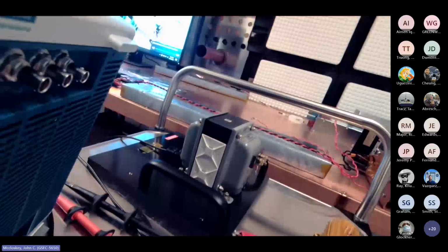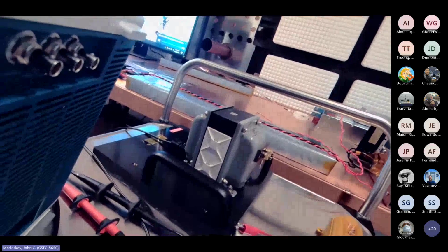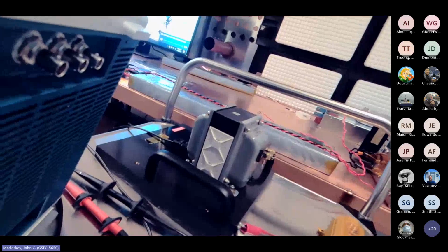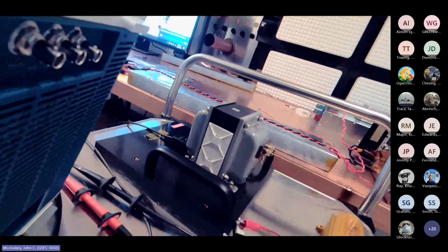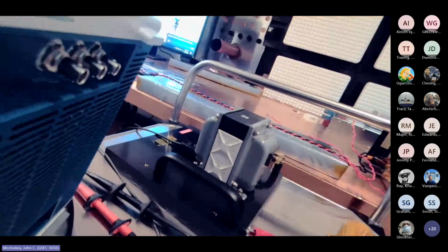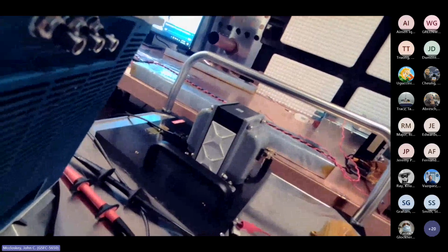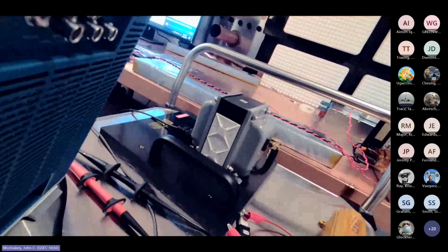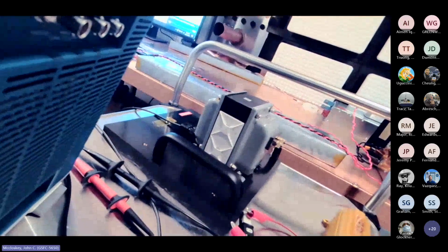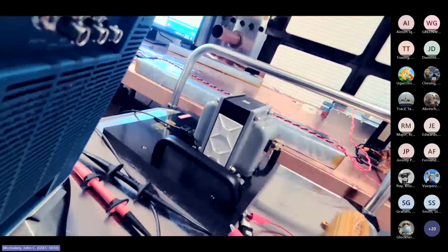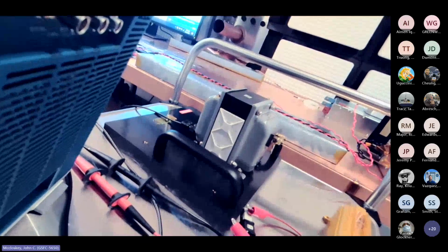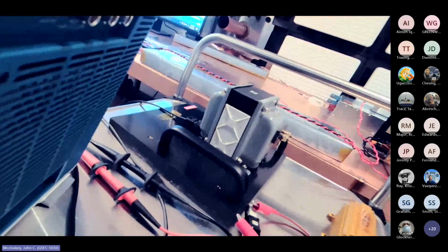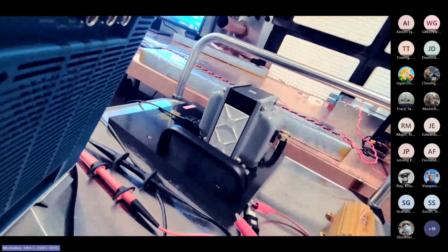So certainly the EMI test engineers need to be clear that we're going to turn on our equipment before the experimenters turn on. But also the experimenters need to be aware of that so that they ask the question, we're about to power on, is your CS101 injection equipment fully powered on and ready? So it's just encouraging everyone. So even if you're not an EMI test engineer, just being aware of the test method sufficiently to ask that question, because it's everyone's responsibility to make sure we do this test safely.